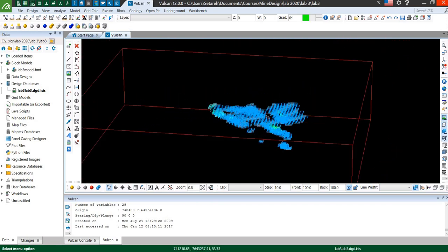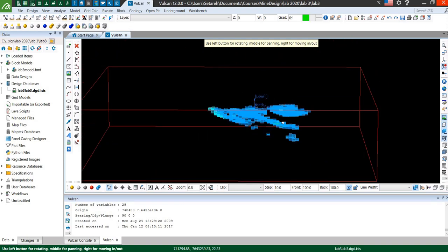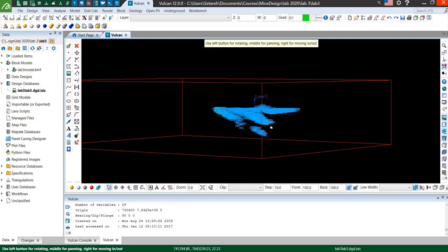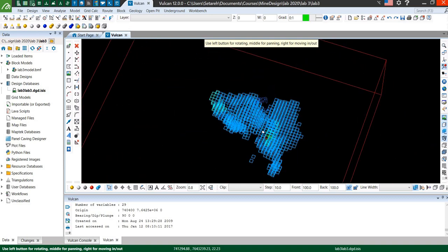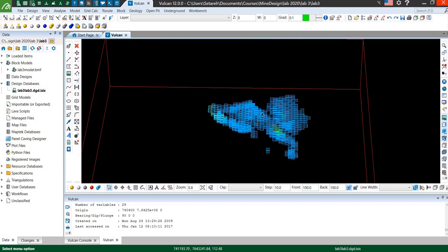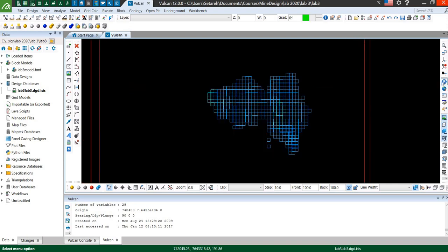Another shortcut is that if I just quickly want to rotate the view without selecting a new rotation center, with the previous one, just hold Alt and with holding the left click on the mouse, you can rotate it. And when you push your finger off of the Alt, then it's out of the rotating. And when you want to reset the view to the plan view, just click that.